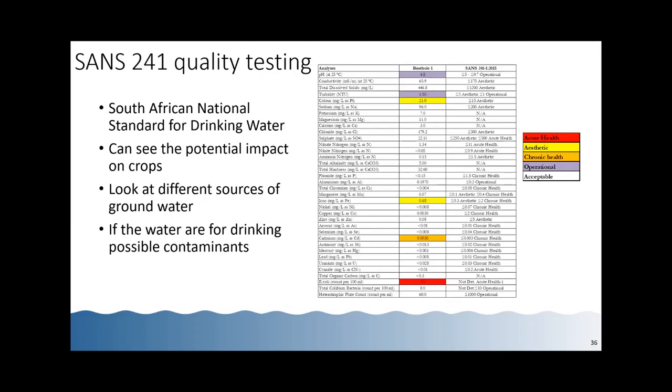So at the end of the test pumping period, at the end of the constant discharge test, we often take a groundwater sample at that point. The point of taking the sample is that the borehole has been well flushed and cleared of anything that was left over from the drilling. And now the groundwater that is coming out of the pump is representative of the aquifer that is surrounding it.